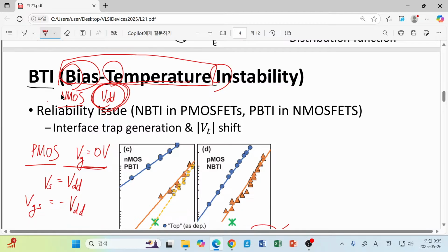So the gate oxide of our PMOSFET is also highly biased. In both cases, although the actual voltage value is different for different devices, it is certain that in this bias case, we try to apply a high electric field in our thin oxide layer, and the temperature is also intentionally elevated to, for example, 125 Celsius.